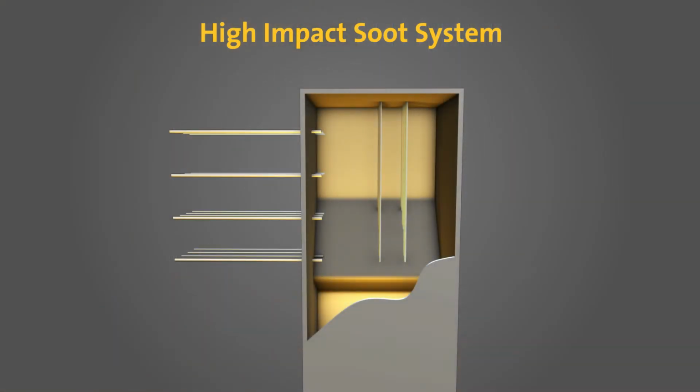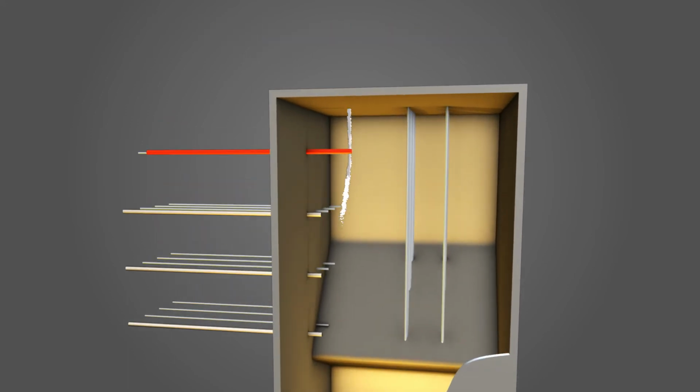Heat Management has developed a patented technology called HISS soot blowing, where HISS stands for High Impact Soot System. HISS soot blowing is based on the potential that half of the cost and issues related with soot blowing are unnecessary. HISS soot blowing is a refined version of one-way soot blowing. The soot blower steam poppet valve is controlled so that steam flow only occurs in one direction and is coupled with a patented control system where the soot blowers are operated overlapping, forward and reverse.